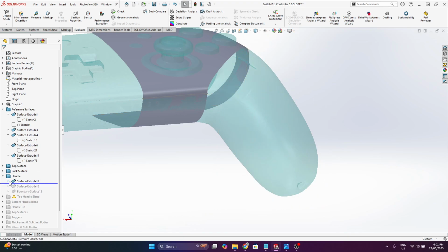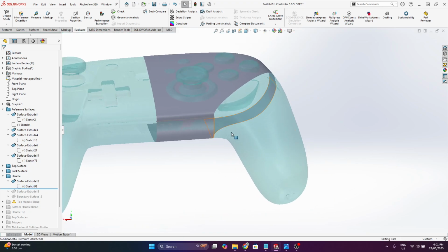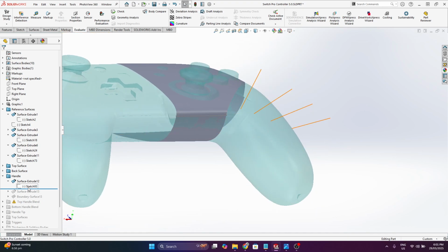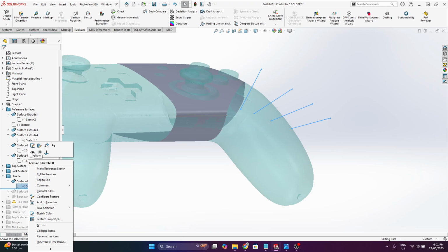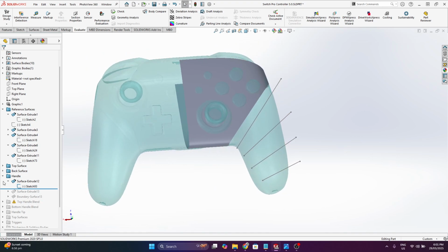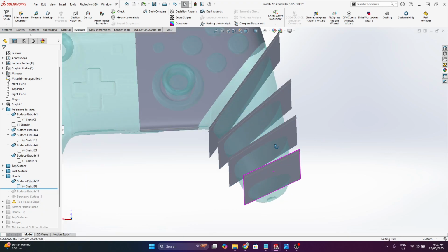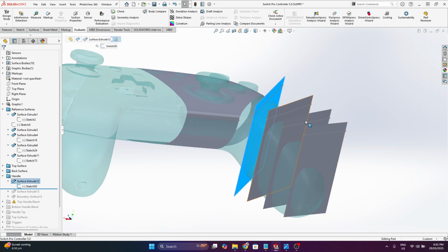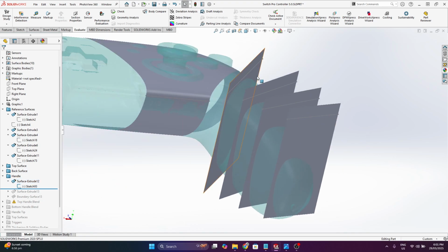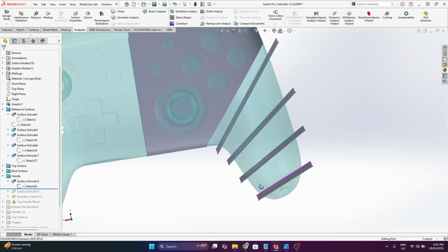I knew I would need multiple planes to build my 2D guide sketches off. And a nice trick you can do is that instead of going through and adjusting planes and repositioning them each time, you can just draw a 2D sketch and extrude that out to give these surfaces, which I later use to draw sketches on. You can use these as you would use a plane. It just really helps when you want to quickly get different kinds of angles to build off.